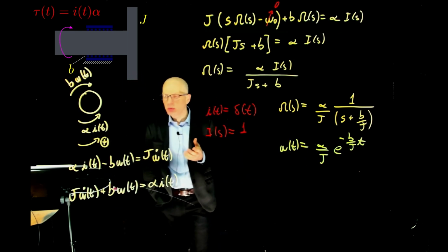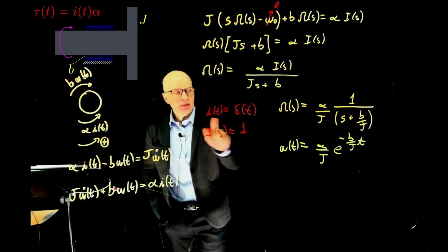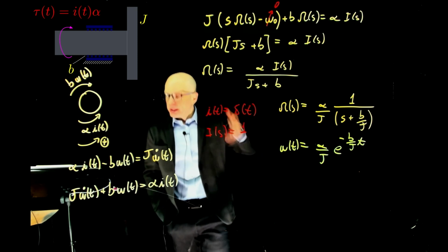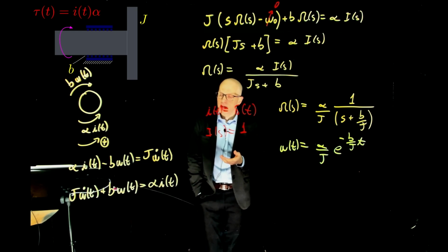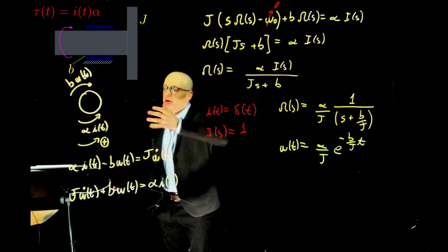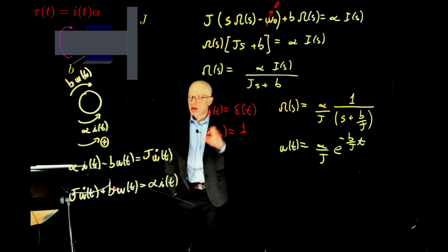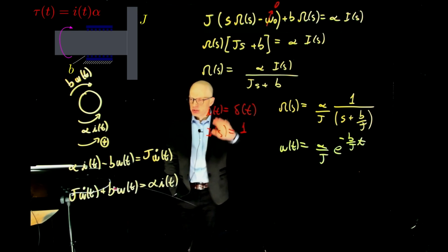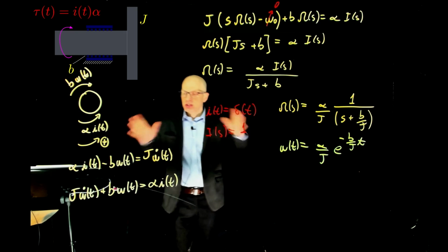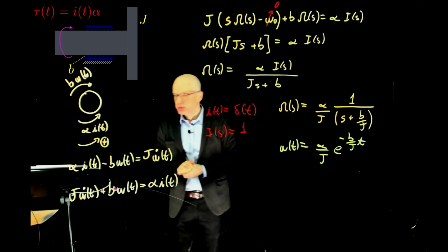The impulse response assumes that at time 0, a delta function that tends to infinity is applied to the system and removed immediately after. You can think about this as applying a very large amount of torque for a very small amount of time and then letting it go, basically slapping the system, letting it move, removing any excitation and seeing what happens. That would be the impulse response.